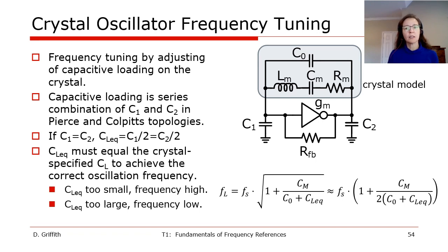If you have an oscillator where the frequency is wrong, you can calculate the error in the load capacitance by using the frequency tuning equations shown on this slide.